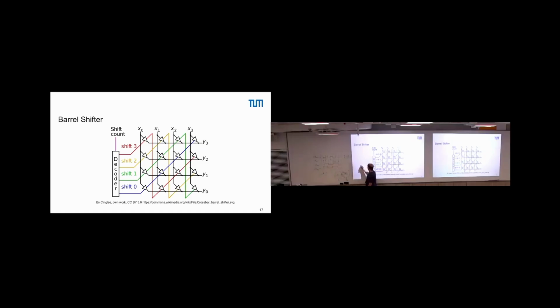Effectively, you take your NMOS, you take a PMOS, and then you have an inverter inside. Here a select signal, here input, here output. If my select signal goes high, I connect input to output. If my select signal goes down, I disconnect input and output. Okay? That's called a pass gate. So it's just a switch that we can implement. You have 2 of these transistors to have full swing from VDD to ground at the output, but that is not so important for us.